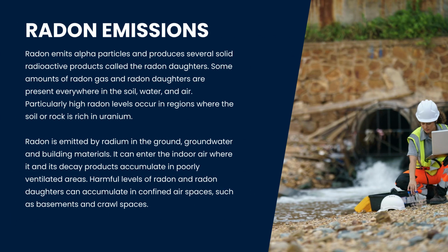Radon is a naturally occurring radioactive gas that forms from the breakdown of uranium in soil and rock. As it is released, it produces additional radioactive particles known as radon daughters. These particles exist in small amounts in soil, water, and air, but levels can increase significantly in areas with higher uranium content. Radon can enter buildings through foundations and construction materials, especially in poorly ventilated spaces where it can accumulate